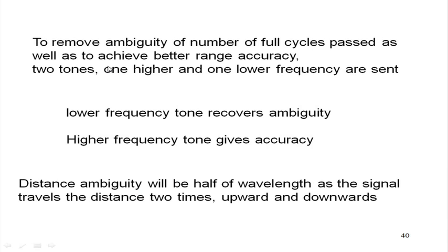We will continue our discussion on space segment, particularly the bus of the satellite, and we had already discussed the attitude and orbit control system, AOCS, and then we came to telemetry, telecommand and tracking. Out of that we have covered telemetry and telecommand briefly, and we were discussing tracking. Just recollect, for tracking there is some problem we are facing: when we send a tone, we get a certain ambiguity in the number of full cycles that has passed. We do not know that count.